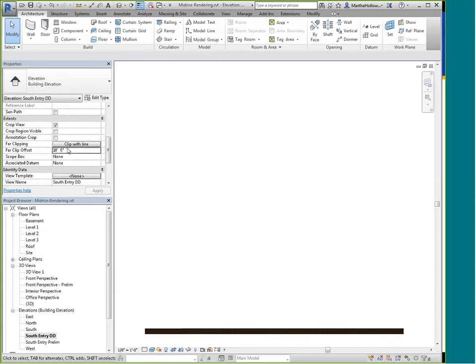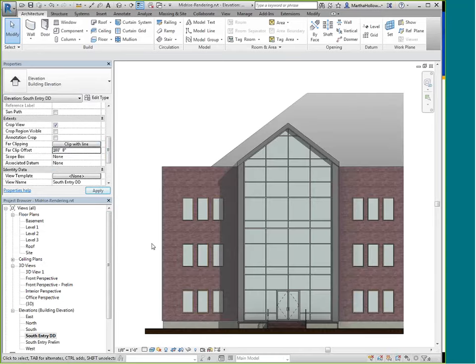So what I need to do is come back here and change my clip plane, the offset. So I'm going to set it to 100. We got a little bit, but can you see how far away it is? So it's all considered kind of far away. What happens when I go to 150, a little bit darker, 200. Okay, so you're starting to see a little bit of the depth changing there when I put on my FAR clipping and set the offset.